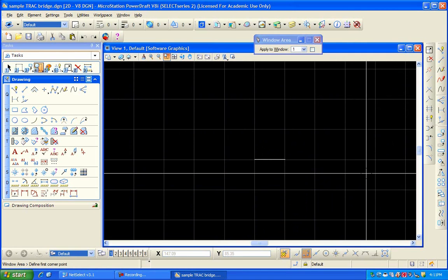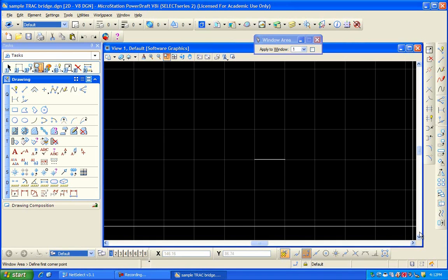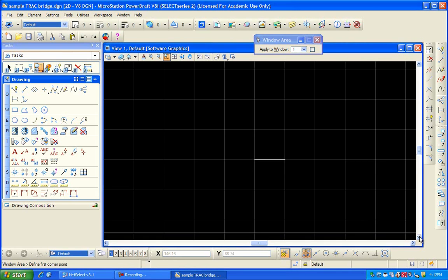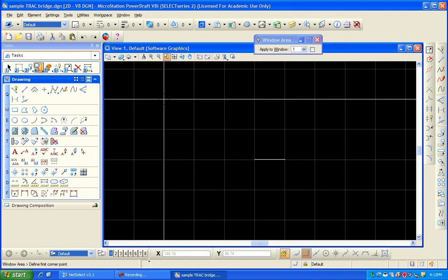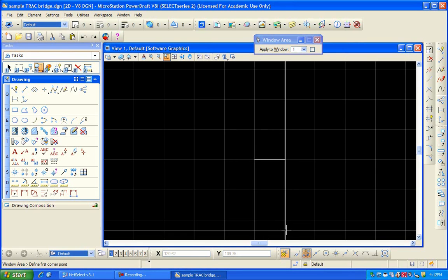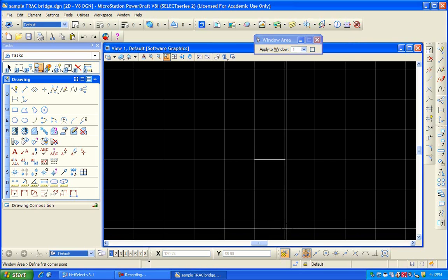So one last thing I want to show in here in the drawing view to help get me set for my sample bridge drawing is I want to create a border that, when I print it out, I can snap on it and create a good printout for my bridge. And what I found for the size of bridge I'm going to be working with, I found if I print a border of 40 inches wide by 50 inches long, that size rectangle, I can fit everything I need on this sheet and come out with a good printout.